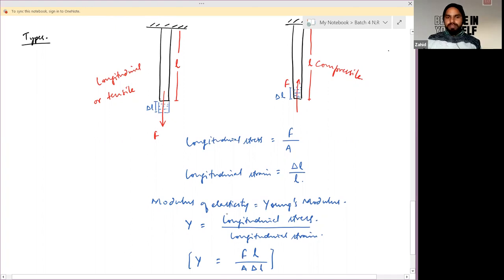Now, this modulus of elasticity or Young's modulus mainly depends upon two factors. First is nature of material and second is temperature. It will be independent of dimension of body and it defines the elastic behavior of that particular object. So here in Young's modulus, it is defining along its length. So you'll say Young's modulus defines the elasticity of a body along length. Is it clear?